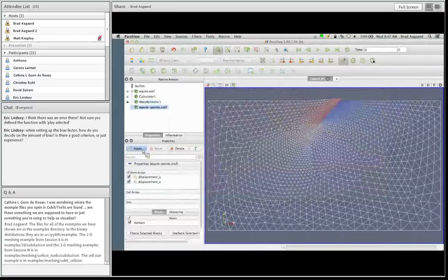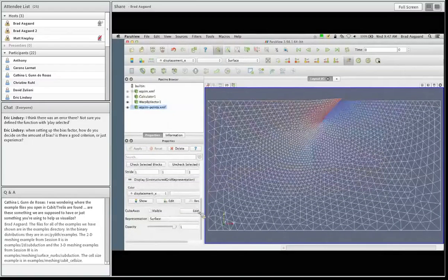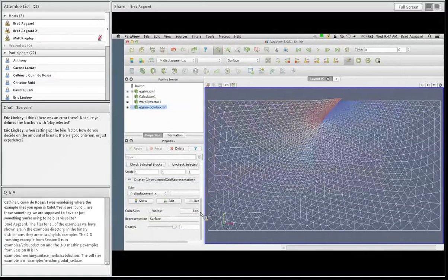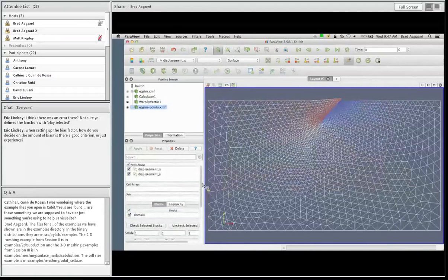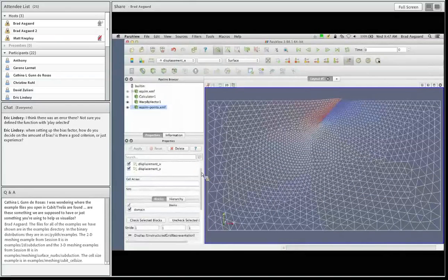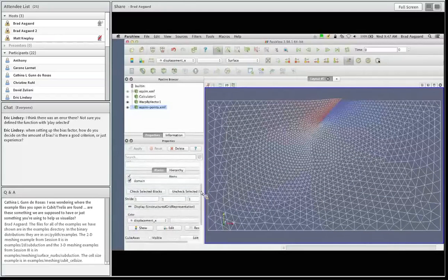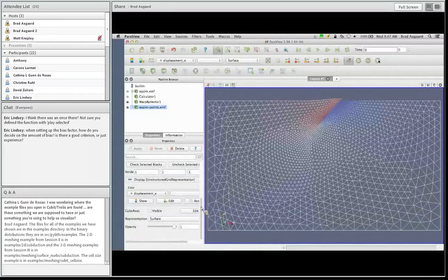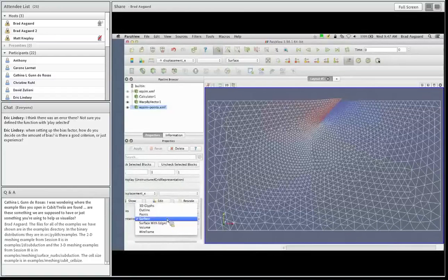And there's point size, so let's make them point size 8. So there you can see the points where we have our observations, colored by X displacement, or if we color them by Y displacement. And there's my color bar. My color bar is not centered about 0, so that's why the left-hand side is not all red.